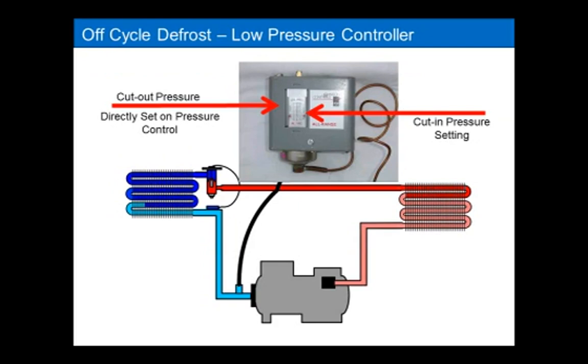So they're not always using differential, but the majority of the controllers used out there do use differential. But watch out, look before you leap. Look at the control, make sure it doesn't say cutout, and it does truly say differential before you start adjusting it.